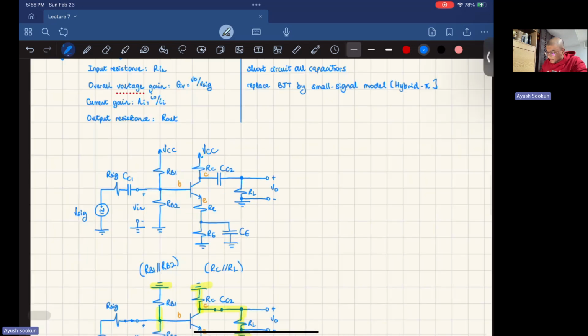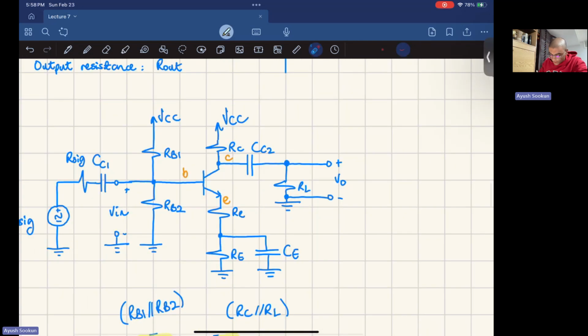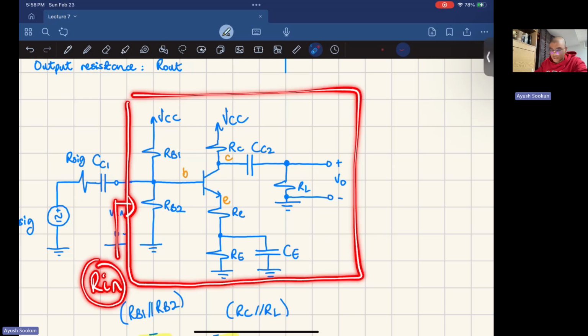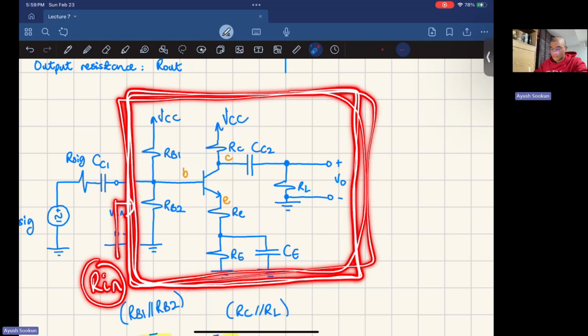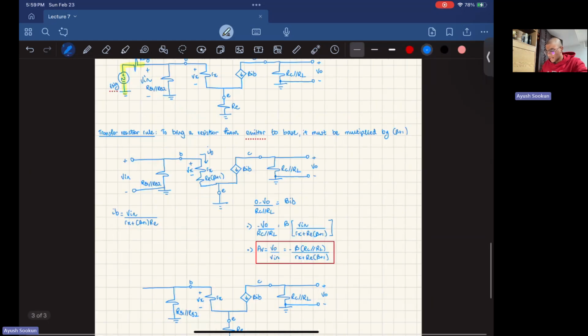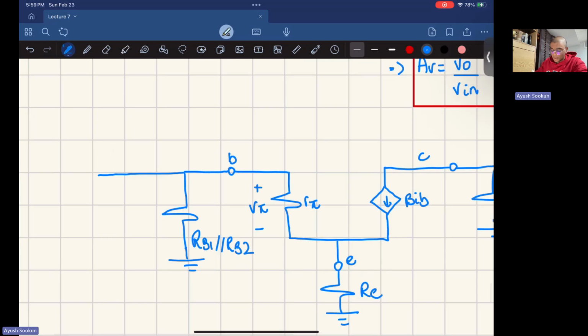The input resistance is basically telling you to replace, you have these terminals right here, you're trying to find Rn, a resistor value that can replace all of the circuit. This is Thevenin. We want to find a resistor value that can mimic all of the circuit, that's going to take the same voltage and the same current. That's our goal. Because if you're working in a lab, it's easier to talk about voltages and currents than a whole circuit itself. The best way to do that is talking about a resistor value. What's the input impedance of the circuit? Instead of talking about how this circuit has this many resistors or this many transistors, it's much easier to numb it down to one thing and then talk about it.